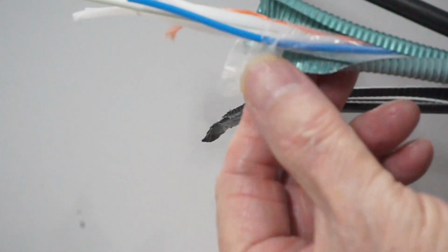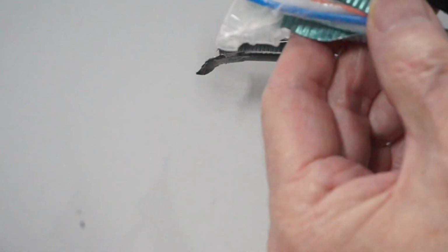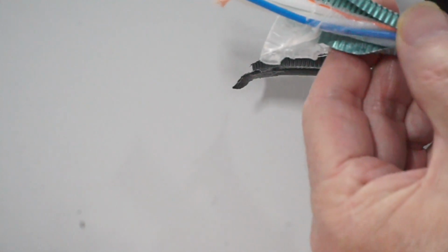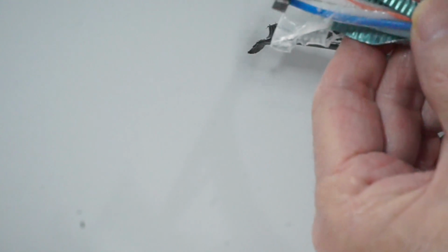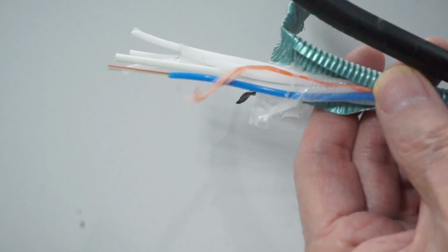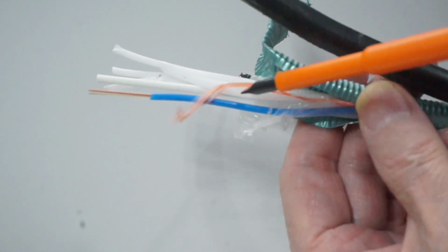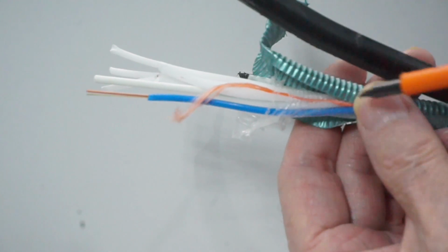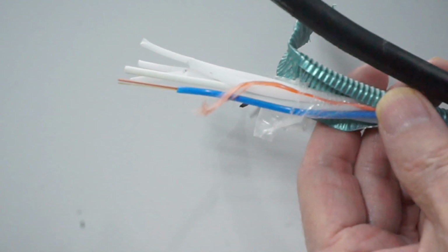Underneath the corrugated metal, there is a very clear plastic covering. Looks like the Mylar sheath, maybe it is, that we have for our type MC cable. There's also a little orange string right there. That orange string is right underneath that clear plastic sheath. We call that the ripcord, and I can grab a hold of that ripcord and pull it back, and then that opens up that sheath for me. Otherwise, it can be pretty tough to get off.